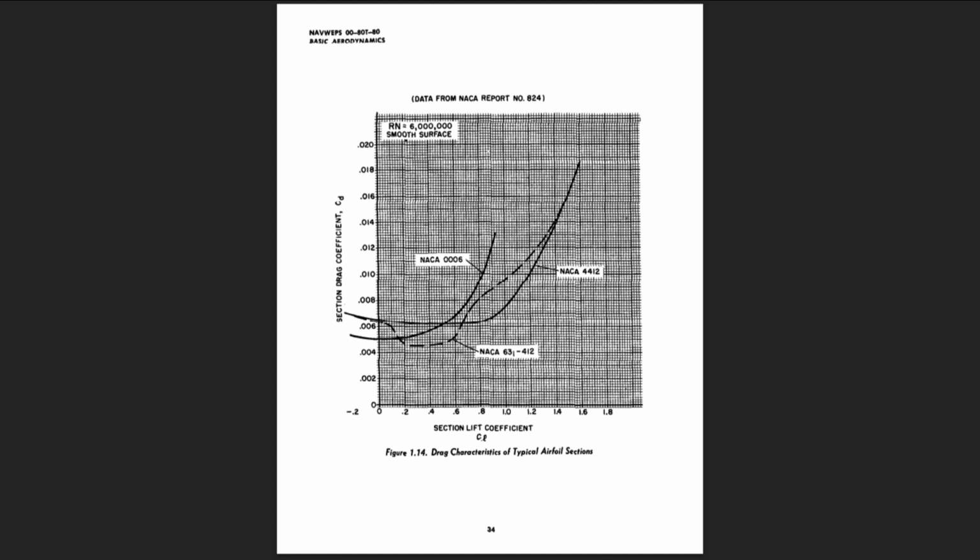The NACA 63-412 is a cambered 12% thick airfoil of the laminar flow type. This airfoil is shaped to produce a design lift coefficient of 0.4. Notice that the drag curve of this airfoil has distinct aberrations with very low drag coefficients near the lift coefficient of 0.4. This airfoil profile has its camber and thickness distributed to produce very low uniform velocity on the forward surface, minimum pressure point well aft, at this lift coefficient.